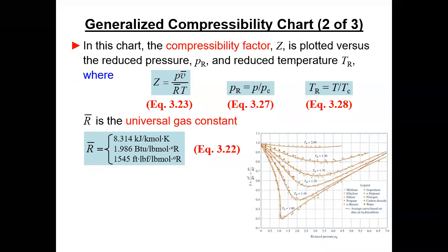And the other thing I remember is if I got PSI, I got to multiply it by 144 because I got to get those blasted inches out of there. So whatever system that you tend to work in, it's good to get enough experience that you remember the pitfalls. Anytime you see PSI, man, that sets off a red flag. You better be reaching for your 144 to get rid of those inches most of the time.